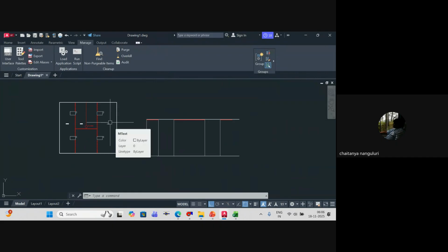Because if you have a fire, the fire doesn't spread rapidly throughout the building. So if it is lesser than 3000, you need not worry about it in the first place. So you don't require a water curtain. No, you don't require it. So that's the reason 80 to 90% of the time you don't see a water curtain system in the first place.